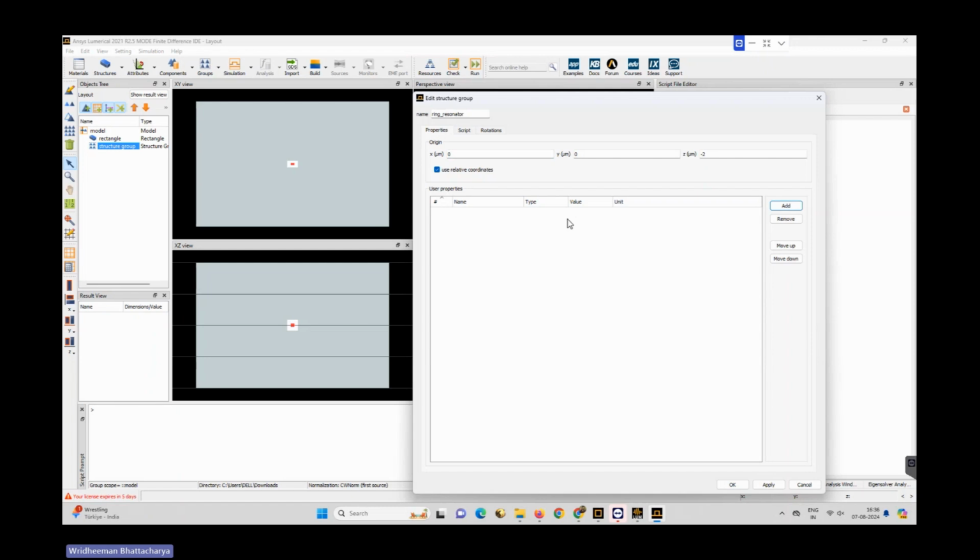So firstly, the name similar should be there here, the one which we have, and here we have to give the length, like the variable LC, then gap length 100 nanometer, now radius 2.1, index number, index should be number, so it will be 3.5.